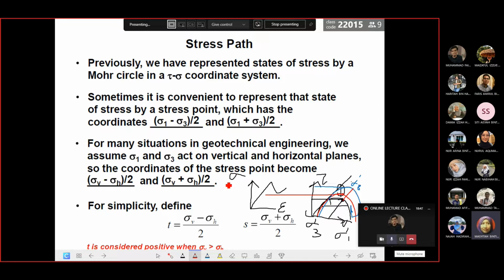This vertical stress, if we do an experiment in the lab, is equal to the axial load, because the axial load is the force we apply vertically when we add load. Remember, when you do a triaxial test, either UU, CU or CD, you have a plunger at the top where we increase loading. As the load increases, the sample starts to fail, until it meets the failure point, it will collapse, or in the case of this sample, it will show some sort of crack on the surface.